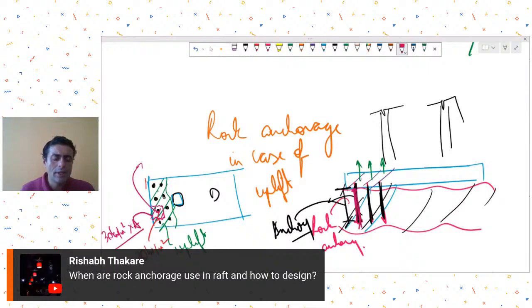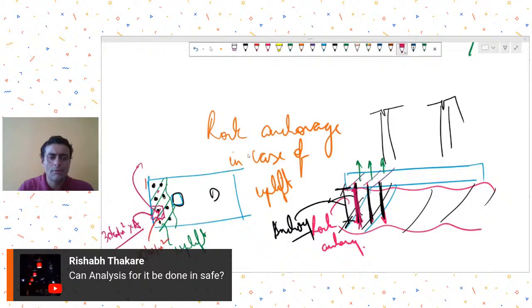And if not, then you can increase the grid spacing, you can reduce the grid spacing, or you can increase the anchor dia, etc. So this type of calculation you can do, and it should also be coupled with actual testing. So pull-out testing should be done on site to just check what is the tensile force each anchor can resist. Okay, so this is a rough calculation you could think of doing.